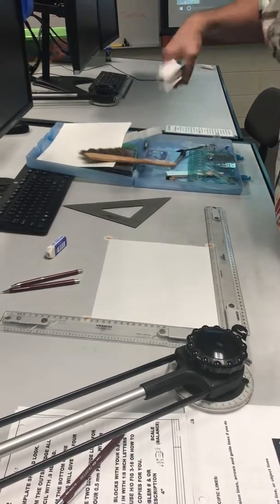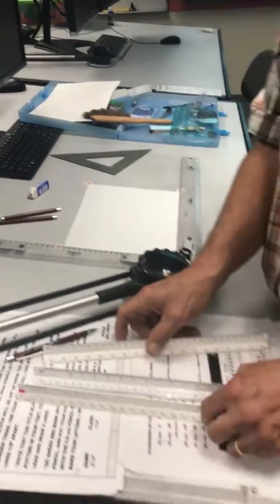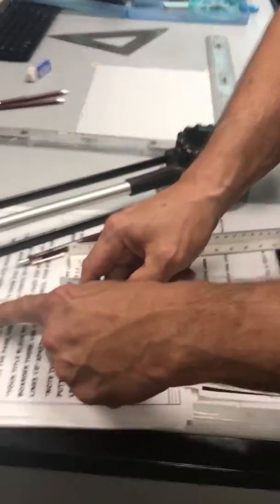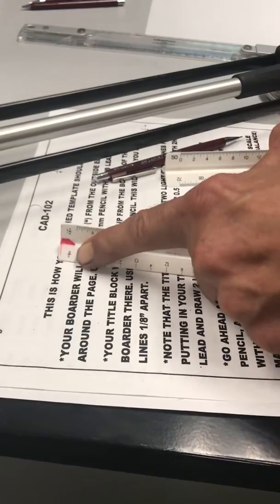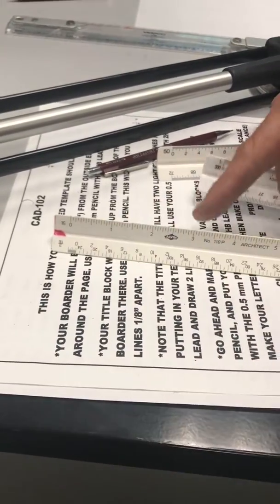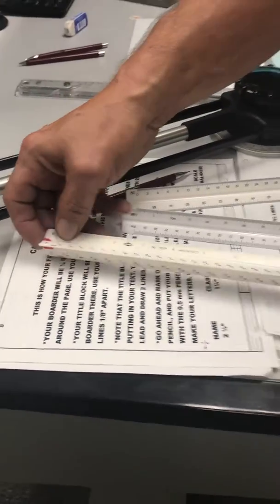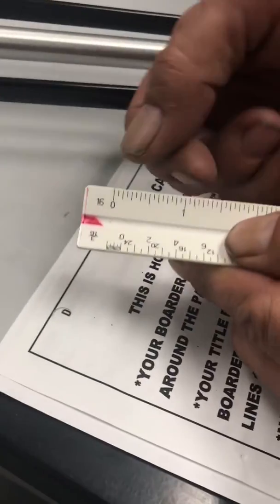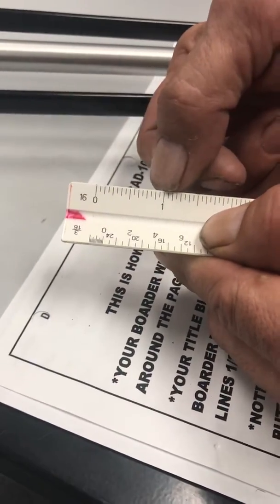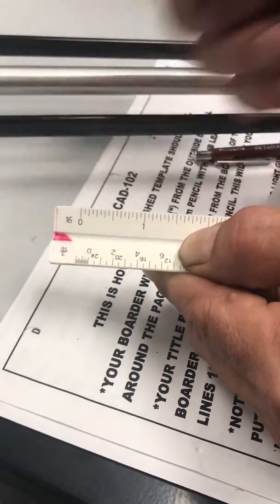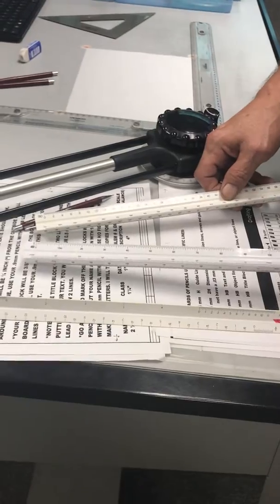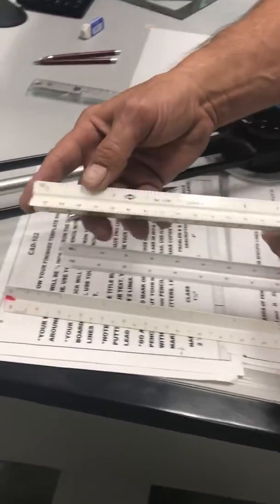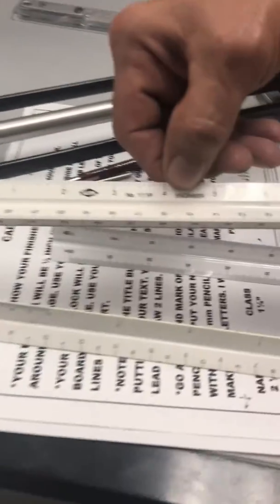Okay, guys. You're going to have an architectural scale, which is going to have fractions on the ends, like so. All right, now when you're just wanting to do the 16ths, you're going to use the 16 side. So these are broken up into 16 ticks, each tick being 1/8 of an inch. Okay, and this is going to be your metric, and this is your civil or your engineering. See, it says engineering on there right there.